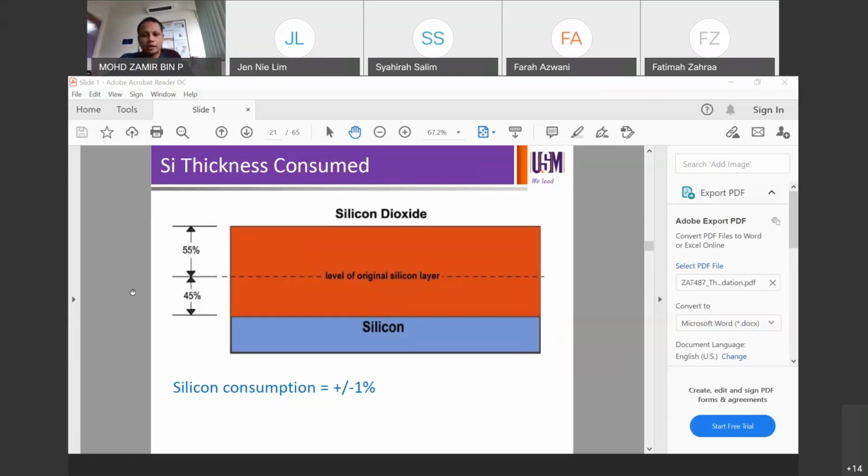So, is it understandable? Do you understand the difference between having your SiO2 by thermal oxidation versus deposition by thin film methods? Is it okay? Understood or not clear? Okay, clear, right? So thin film deposition does not consume your silicon, but thermal oxidation consumes your silicon.